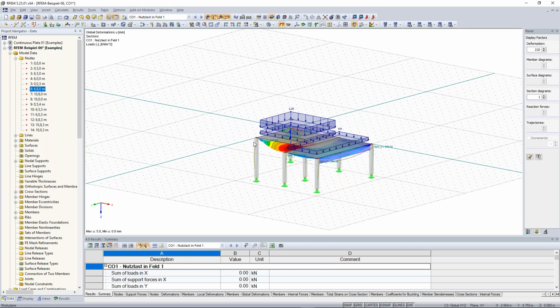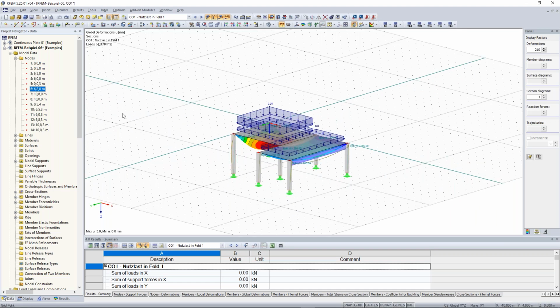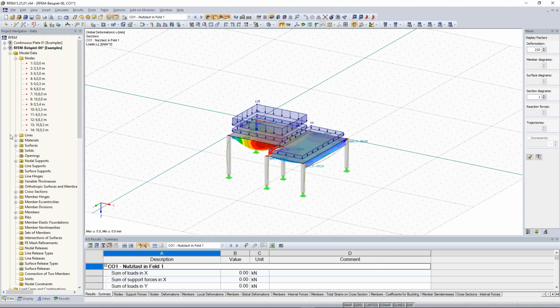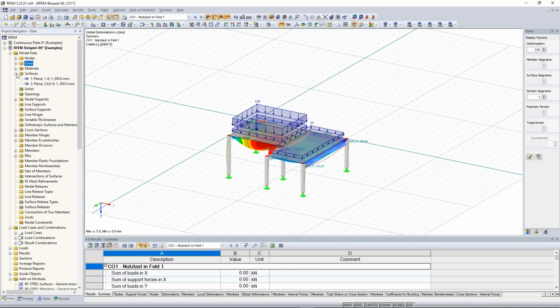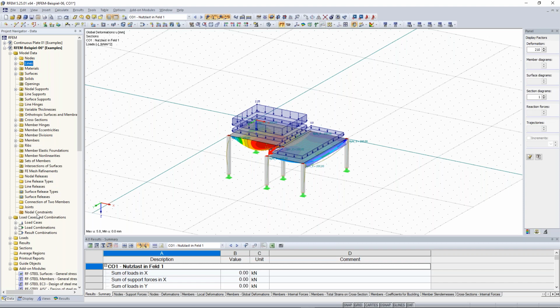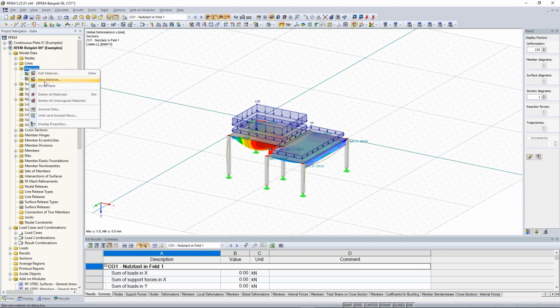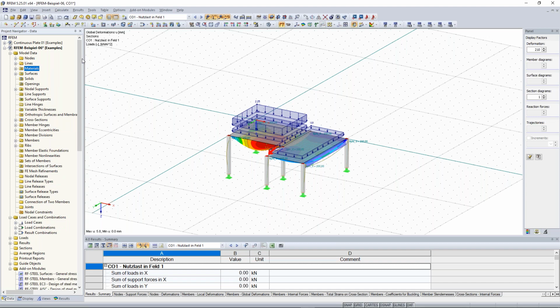And if I click on that, I can't see it really in the model. No problem. I right-click on one node, I can find it, and a red arrow shows me where I can find this node. I have also lines here, nodes, surfaces, materials, and so on. I think this helps you to have a good overview of your project, of your objects, but also a smooth way to create something like that. So if you create a lot of materials or something like that, you can use it. Just click here on a new material, and then you can enter and insert a new material.